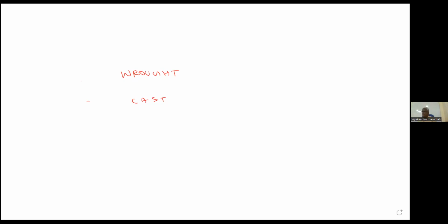Okay. Now coming back to the physical properties, as a welding inspector, the important one is conductivity. Heat conductivity. Now the question is, is a high conductivity material easy to weld or difficult to weld? The answer is difficult to weld.